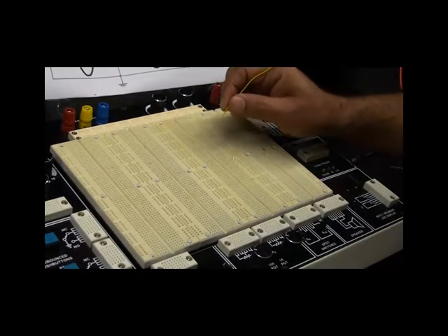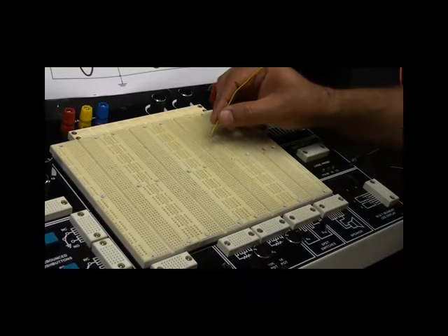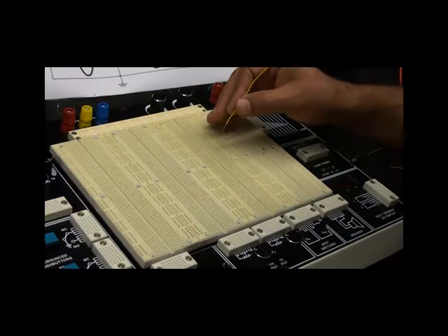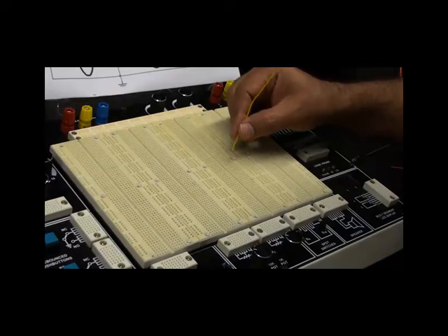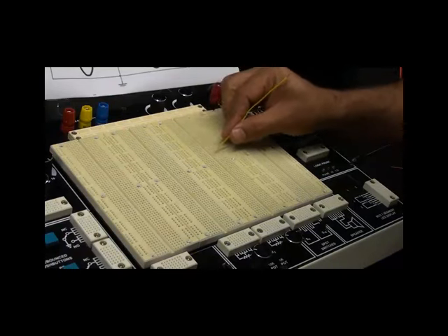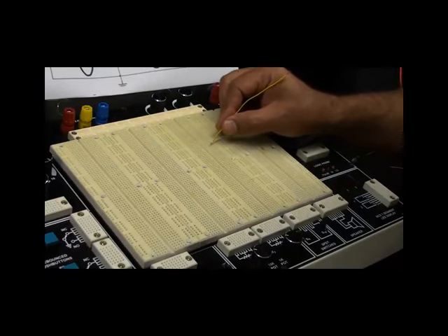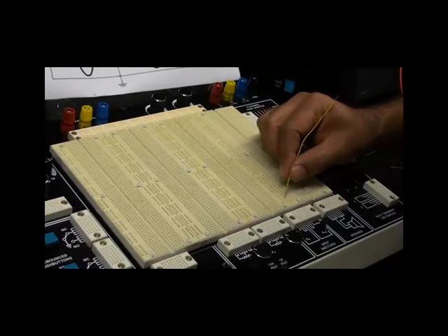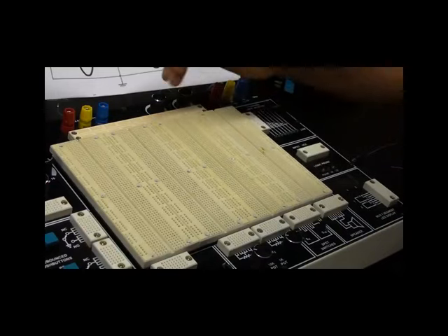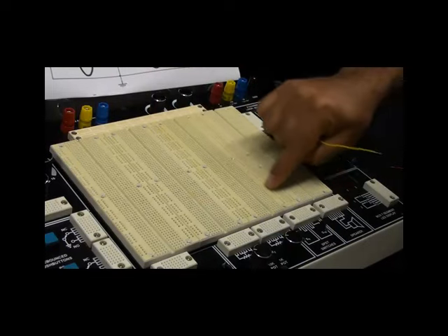The breadboard is there to avoid as much wire as possible by just using the connected holes together, so that we don't have to connect them through wires. So we have to find out how the holes are connected together. The holes in the middle are connected in the column, so vertical columns are connected. The holes on the side, which are the two sides of the breadboard, are connected horizontally.